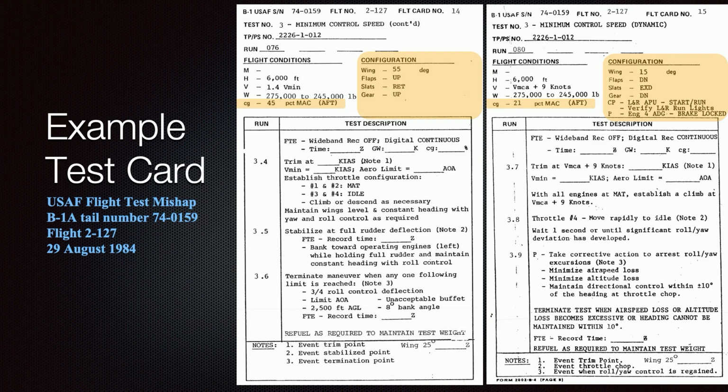The additional factor was lack of attention in mission control to the transition between flight cards 14 and 15. Prior to the mishap, the aircrew repeated flight card 14 because the first attempt did not have adequate data quality. The mission control team took advantage of the downtime between transitions between flight cards 14 and 15 to review the data from the second attempt at flight card 14. Those personnel not reviewing flight card 14 data were working to stay ahead of the aircraft by preparing for flight card 15, and although mission control personnel had the data for wing sweep angle and longitudinal center of gravity available, in theory they could have advised the aircrew of an impending out-of-envelope condition. Nobody was actually monitoring the transition.